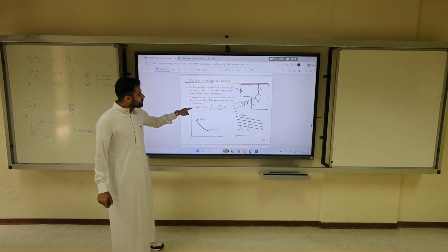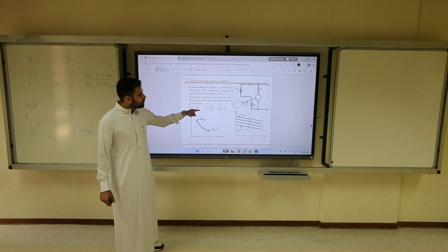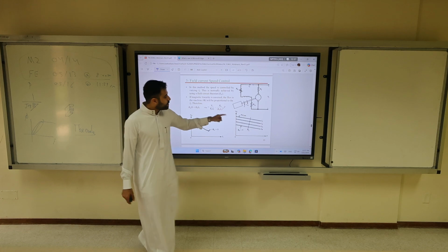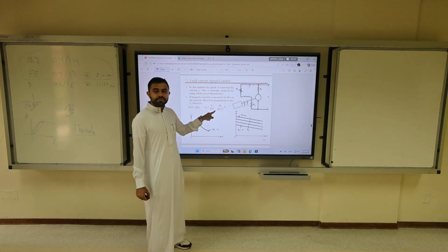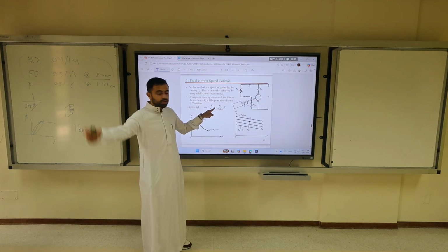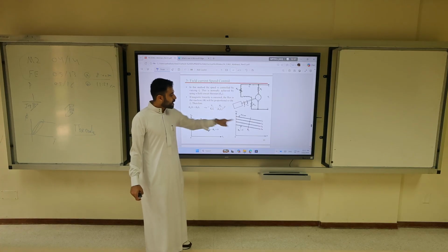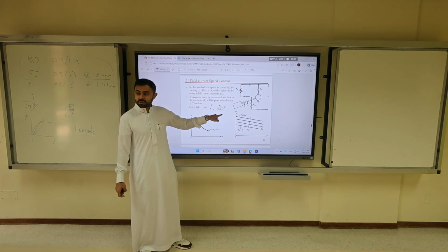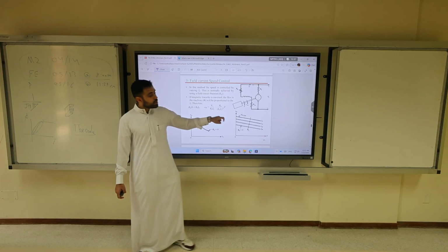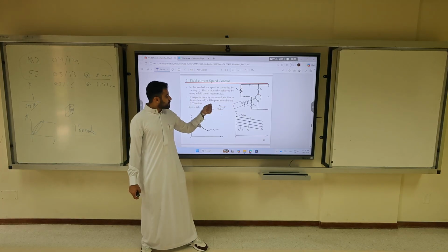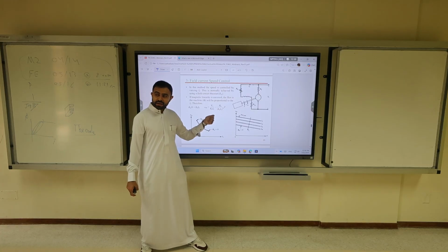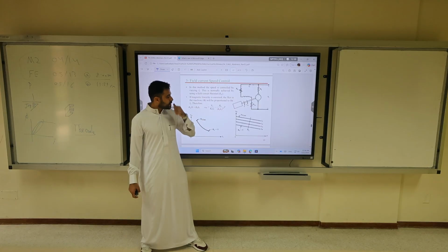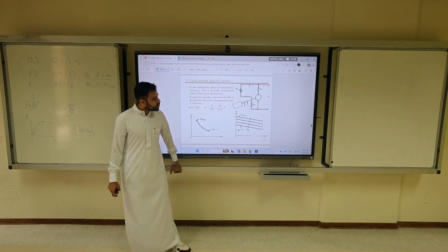Therefore, Ki times flux equals Kf times If. Substitute with If and then you have the speed curve. What will happen if you increase IF? Osama, what will happen? If you increase IF, speed will decrease. Why? Because the subtraction has the square. Akbar: It's Vt over, if you make IF bigger, it will be small, minus. Yes, so the speed will be smaller.